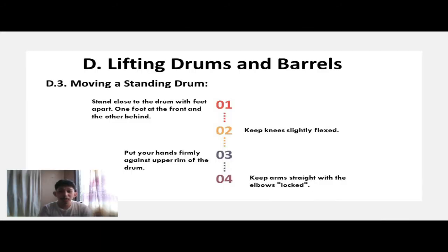Now that you are able to learn the steps or the processes that you need to do to be able to raise the drum, it is now time for you to learn about how to move a standing drum. So, the first thing that you need to remember is to stand close to the drum with feet apart. One foot at the front and the other foot behind.